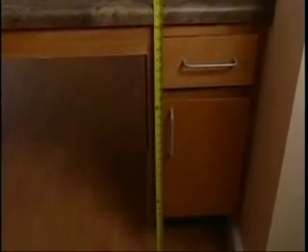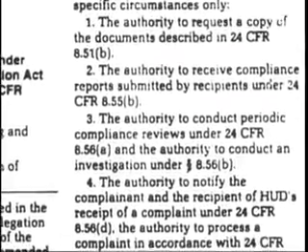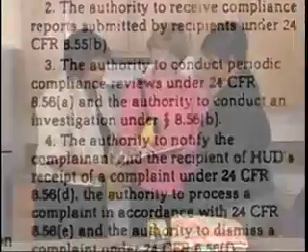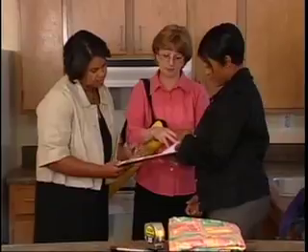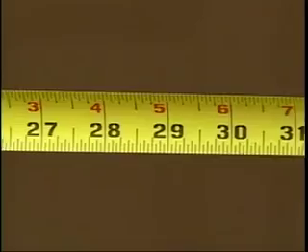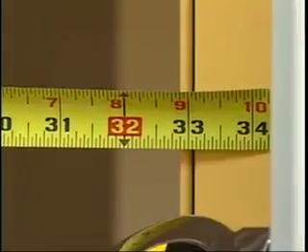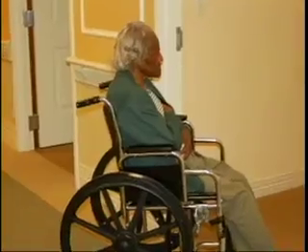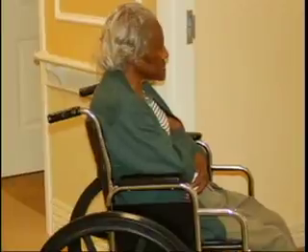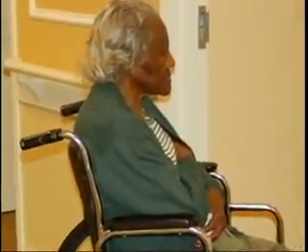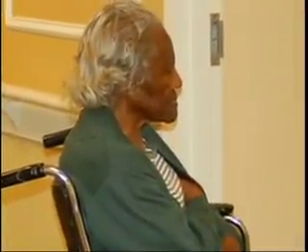When we go out to measure various elements of a dwelling unit, we are looking to see if the minimum requirements for access are being met and complied with. While it might seem that being particular about a measurement being off by 1/4 of an inch is no big deal, it actually can mean the difference between whether or not an individual with a physical disability can enter a dwelling unit door using a wheelchair, for instance.